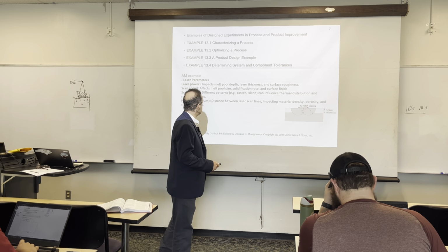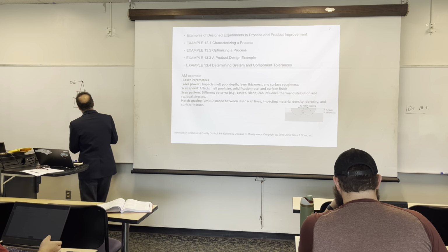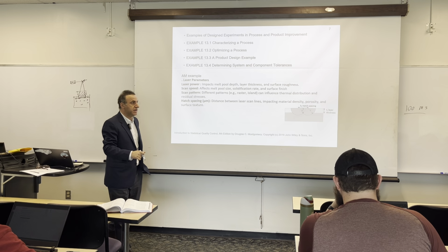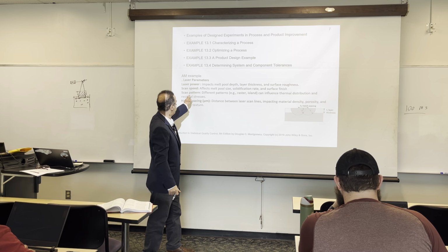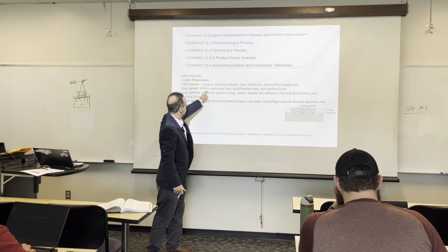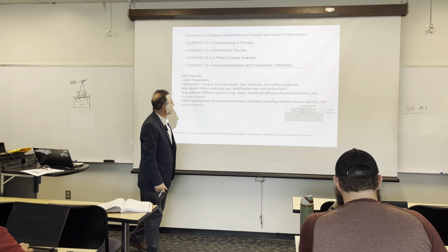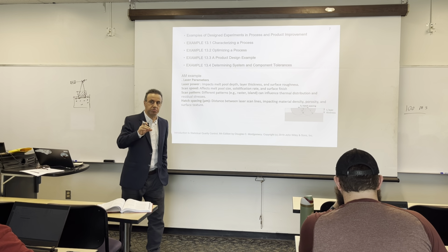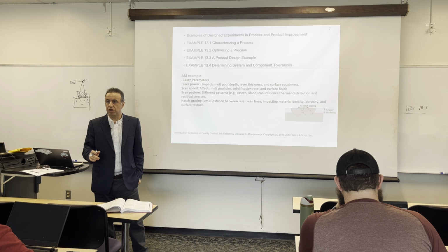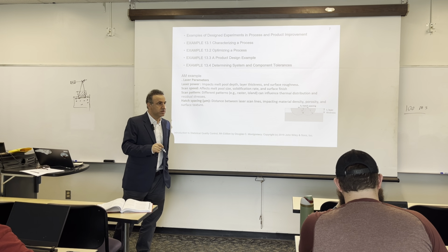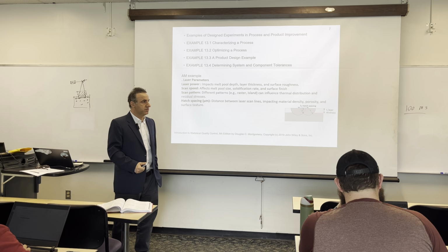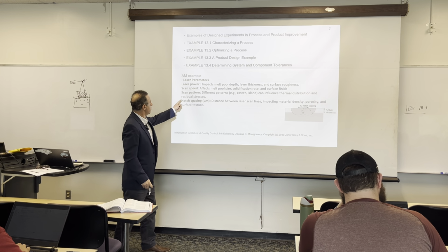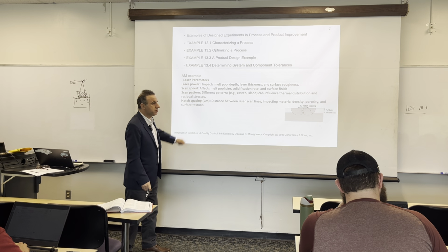If you have faster scan speed, the scan speed comes from this mirror, how fast that mirror can rotate or move. That is going to affect the scan speed. Then it affects the melt pool size and solidification rate, how fast your part is going to solidify. Those solidification then affects the strength, hardness, surface finish, or scan pattern.